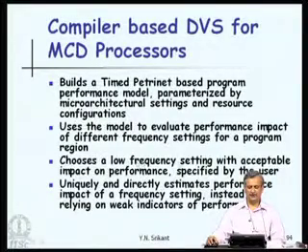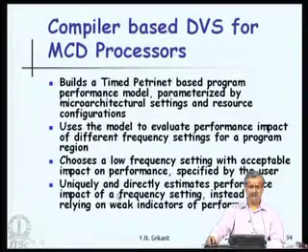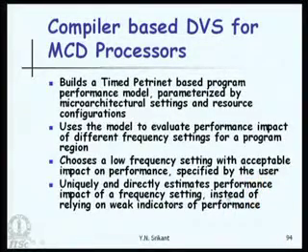Using this duration based simulation, it is possible to evaluate the performance of the CPU at various frequencies. So, we choose a low frequency setting with acceptable impact on performance, and this impact can be specified by the user. The advantage of this particular scheme is that it uniquely and directly estimates the performance impact of a lower frequency setting instead of relying on weak indicators of performance. So, directly we simulate for a certain duration and measure the performance.